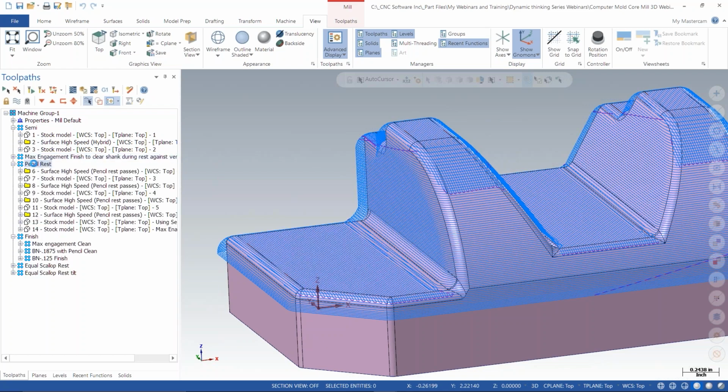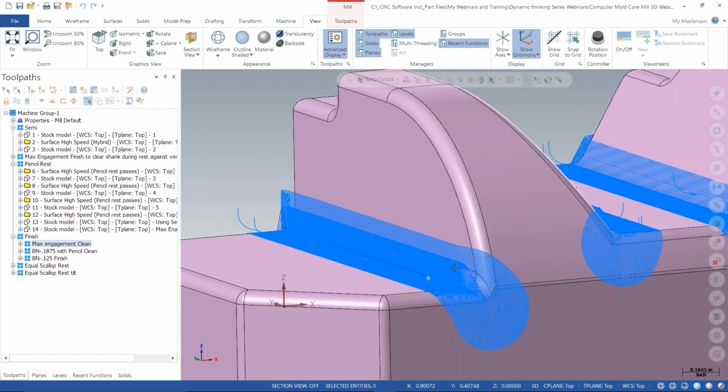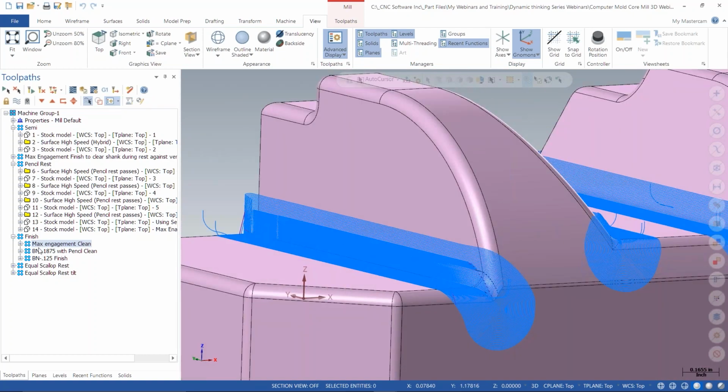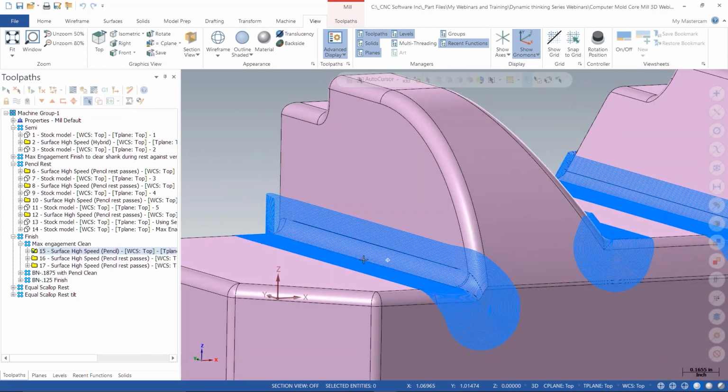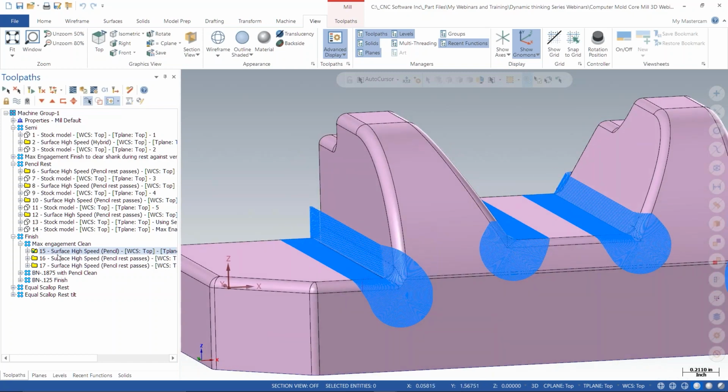So then you dig the corner out down to 5, you leave 5 thou on the part, whatever, and then you run a pencil to final 0 stock to leave, right? But this pencil is not very efficient. Look at all this overcutting. It's the nature of the pencil finish. It just does a number of offsets left and right. Depending on steepness, it can overcut.